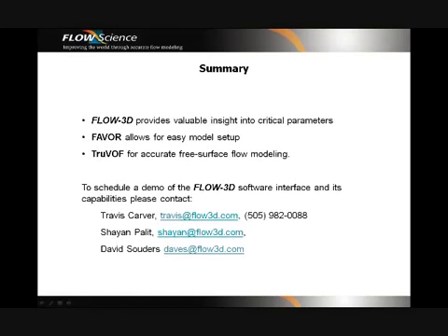Dave, we have another question here that asks, can we model the flow through a fish screen, basically a perforated steel plate that blocks a flow. And that's absolutely possible, as long as we can associate this plate or screen with a thickness so we can resolve it effectively with our computational cells. There's no reason why we can't model the velocity and vortices that are due to the fish screen, to prevent any fish from being trapped or lodged next to the screen.